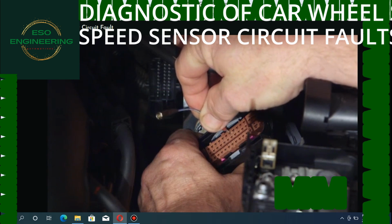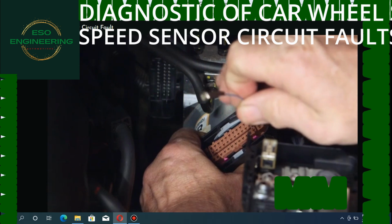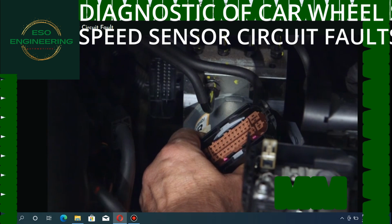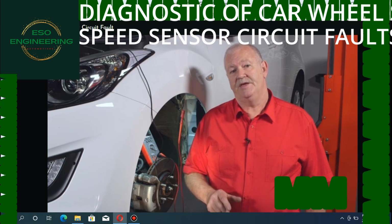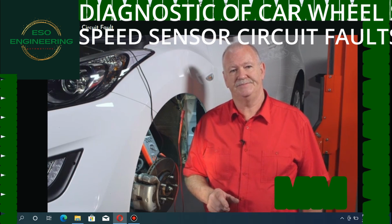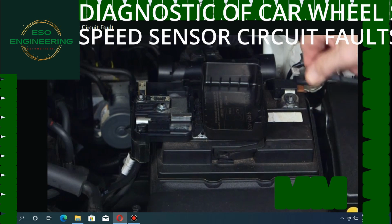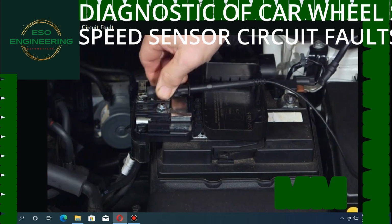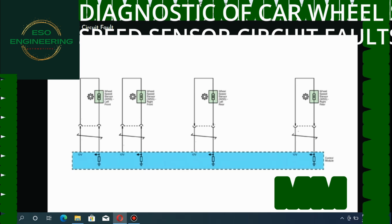The connector can be checked for corrosion and terminal tension, and if this is okay, then the module will be the cause. If there's no voltage at the sensor connector, then it will be necessary to check for a short to ground or an open circuit on the 12-volt reference circuit. To check for a short to ground, move the multimeter lead from the negative terminal to the positive terminal of the battery. A voltage indication here will confirm a short to ground.